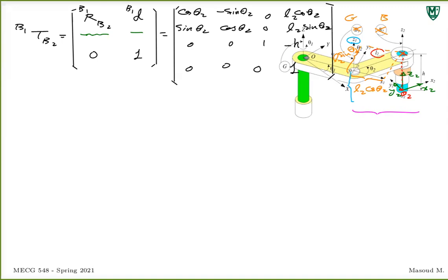The second frame, always think about it as the body frame. The first frame, think about it as the global frame. We always do this in pairs of frames. Always think about it this way: start with where your local frame is. Your local frame is always aligned with your global frame at the beginning of the motion.